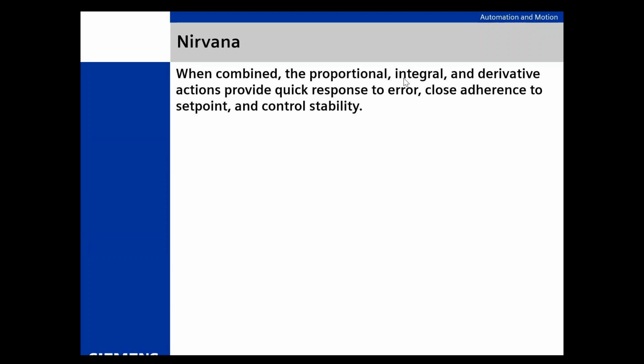But what he mentioned there was pH. pH is very difficult to control. It's hideously nonlinear. If you told me I've got a 5,000 gallon tank of something, and before I can put it back in the river, I have to lower the pH. So here's some acid. And it's got a mixer in there, and there's a pH probe stuck in there. That takes a ramp soak program to do that right. You just can't start adding acid.